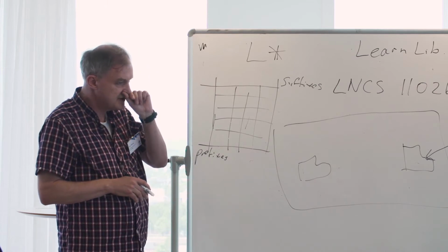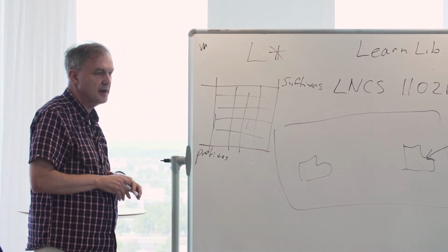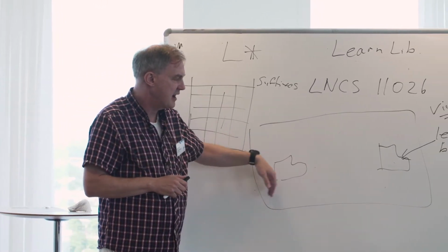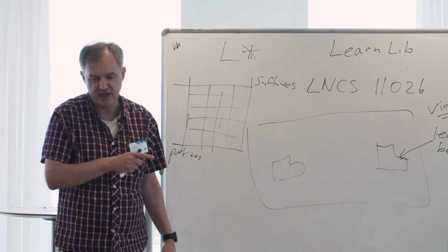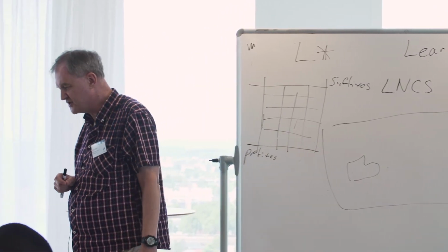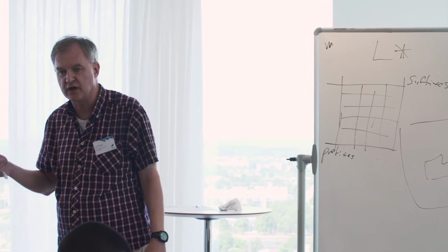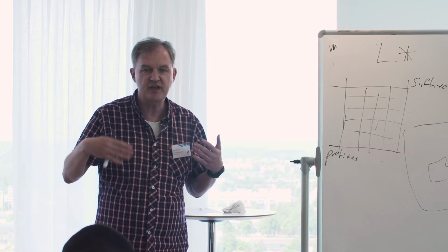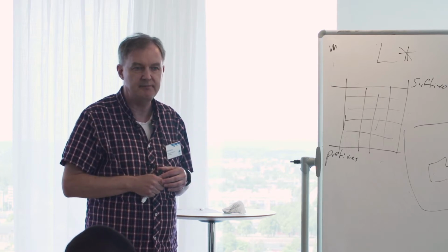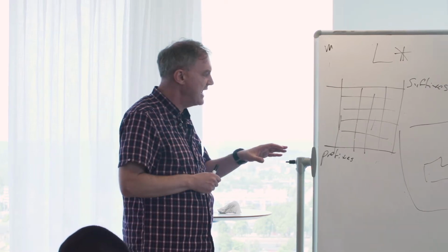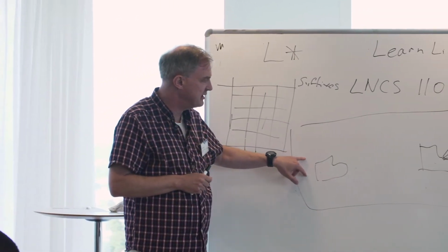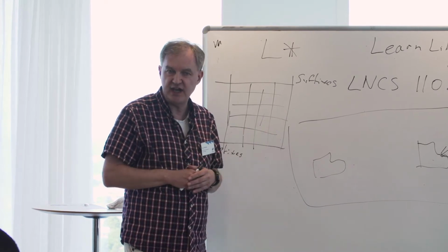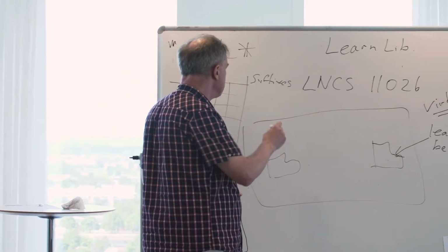So I'm going to show you the results for the very first use case, which is just high-speed cruising. High-speed cruising is something that you can achieve already in a minute. You'll get up to the legal speed limit for most countries, and then you can carry on a bit longer. And then basically the world is going to just repeat itself after that, okay? There's nothing really substantially new going to happen. So you can hope to make a finite state machine model of high-speed cruising if you quantize the time enough. We use 5-second cycles.